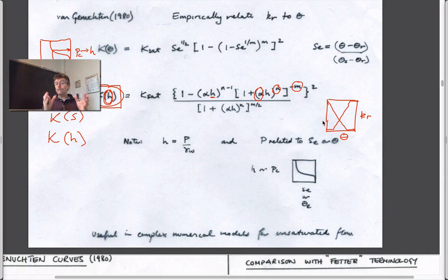How we can use that information to also say something about if we try to remove fluids from it, how we can calculate the rates at which we would remove fluids, and when we'd stop removing fluids when we get to these irreducible saturations at the edge. And also if we're just pumping water through it and dissolving some of the free product in that water, how long it would take for us to completely deplete the system of that component.